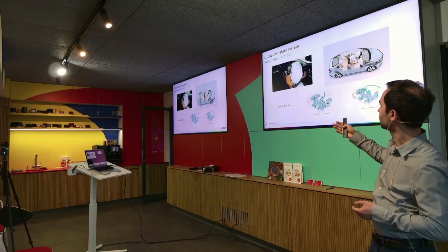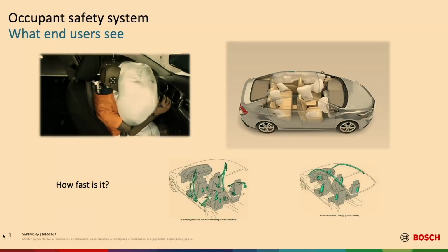And what do we deploy after making these decisions? You can see frontal airbags deploying, or in this picture, almost every kind of airbag. There are also, let's call them, interaction bags between the driver and the passengers, so their heads are not hitting each other. Nowadays, there are even bags inside the belt or in the cushion. There is a headrest bag, so if there is a rear accident, your neck is not hurt that much.